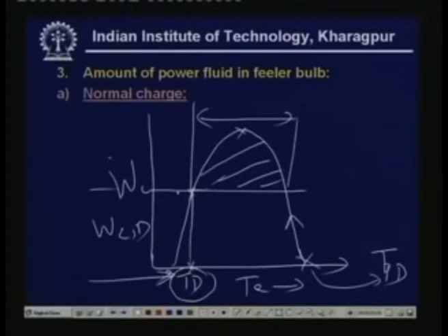This happens, if you remember, because during the pull down time the mass flow rate of refrigerant will be very high, because the compressor volume pressure ratio will be small, so it will operate at high volumetric efficiency, and also the density of the refrigerant will be high, okay. So initially the mass flow rate of refrigerant through the compressor will be very large, even though the enthalpy difference across the compressor is small, okay. Since the mass flow rate is very high, the power requirement will be very high in the beginning, okay. After some time, as the pressure ratio increases, the mass flow rate through the compressor reduces, so the power requirement also reduces, okay. That is how we get this kind of a curve, right. So the power peak or the motor overload is taking place because of the higher mass flow rate, okay.